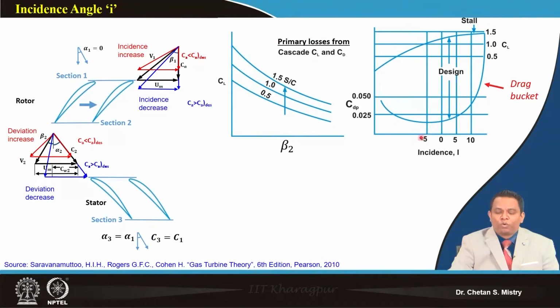Okay, now let's look at the other side, when we are having a negative incidence angle. You can see my lift is still being generated, but it's lower compared to what lift we are expecting. So the meaning is, this is giving us an idea that the pressure rising capacity of the particular aerofoil is decreasing. Okay, so this is what we need to remember, this is very important. And as I told, as aerodynamicists, many people used to say this as angle of attack, but in our conventional language we are writing that as incidence angle.